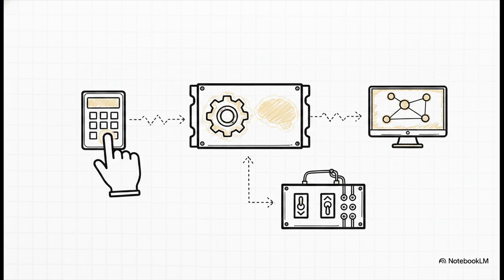Parameter 02.00 controls the source of your frequency command, and 02.01 controls your operation command source. So, are you going to use the digital keypad right on the front of the drive? Are you wiring up external switches and relays to the control terminals? Or maybe you're integrating this drive into a larger network using the RS-485 communication port. Whatever it is, you have to make that choice right here in Group 2.